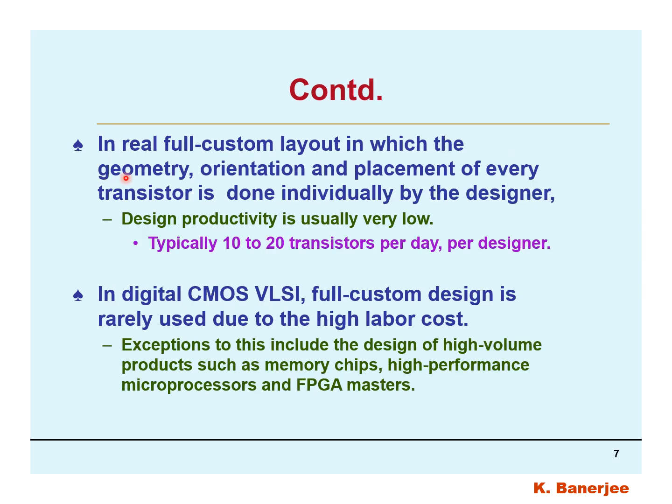The next slide, very important. In real full custom layout, in which the geometry, orientation, placement of every transistor is done individually by the designer, that is by hand, their design productivity is usually very low. It is found from the industry data that typically it is 10 to 20 transistors per day per designer. For this reason, this is not very much acceptable in the industry.